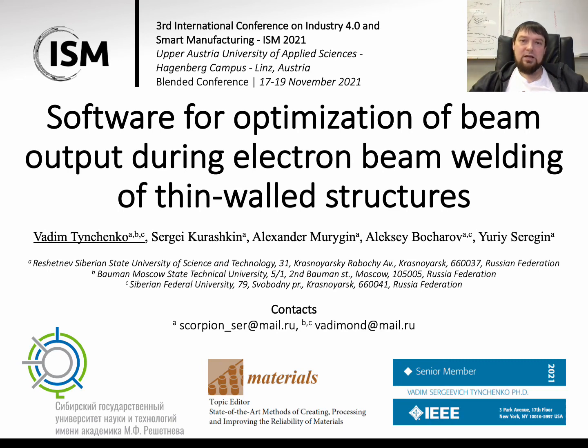So, in the course of the study, the authors developed a model for optimizing the electron beam output mode, which considers the dynamics of the thermal processes in the welding joint zone and depends on the electron beam input mode, the geometric dimensions of the product, and the technological parameters used in the welding process. The prototype of the software system developed by the authors will allow obtaining a stable quality of the welded joint and reducing the number of defects arising in the stage of electron beam